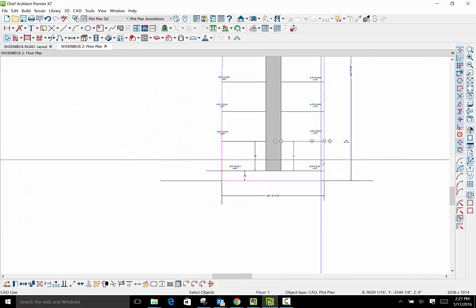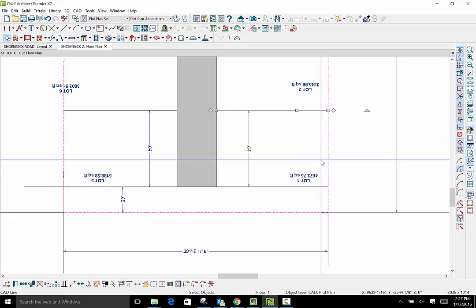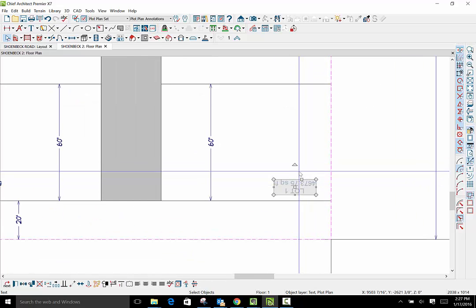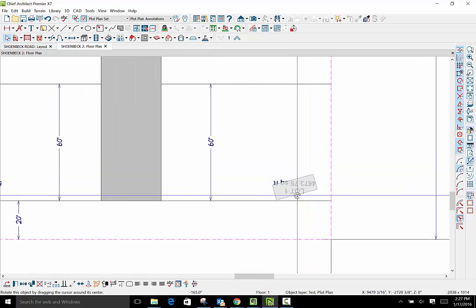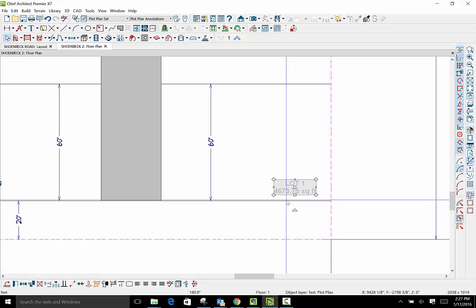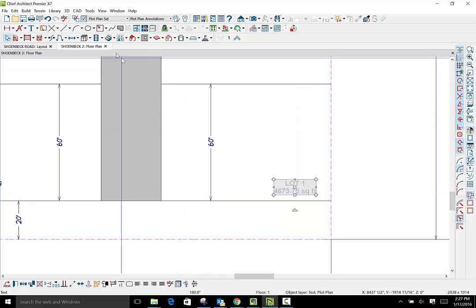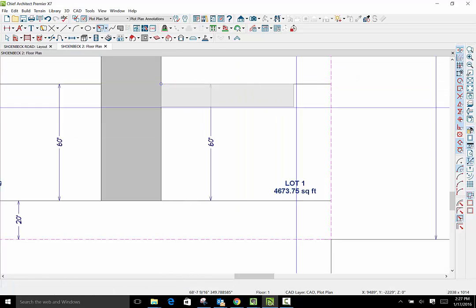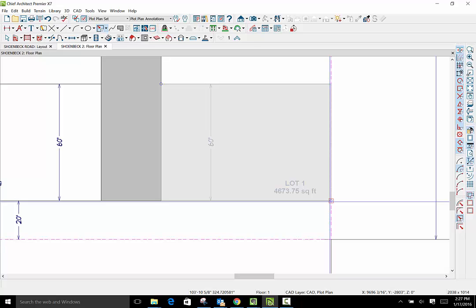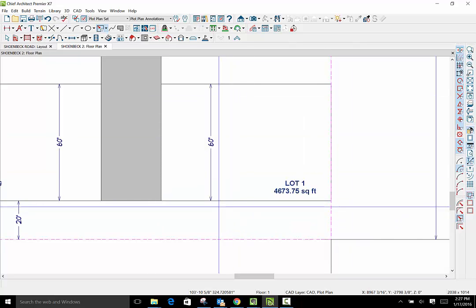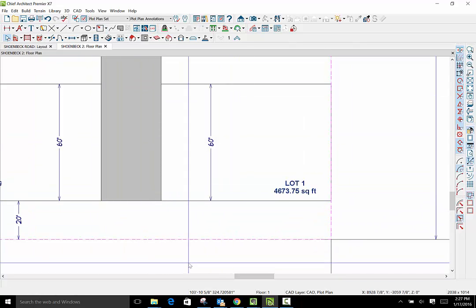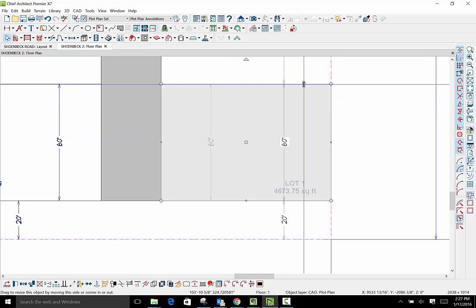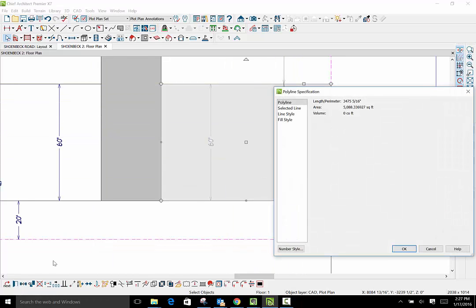And we're just going to reorient this. Flip this guy around. Let's do an area calc. You do an area calc, you take your polyline, snap it there. There it is. That's how big that thing is. They're each going to be the same. We go take a look at some general info on it.